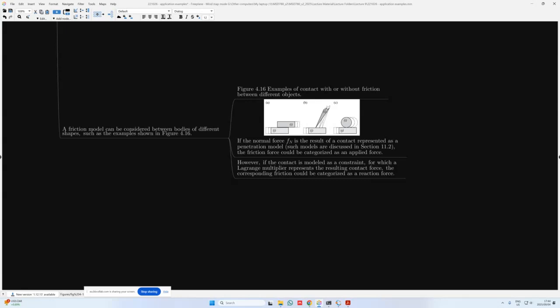And this is case D that we have over here, where we consider the disk joint as an amended form of our friction force model. So the disk joint is a joint, so it imposes constraint equations on the system, and we can go and analyze those constraints as Lagrange multipliers to get our no-slip condition or our friction condition out between the disk and the surface that it's rolling on.